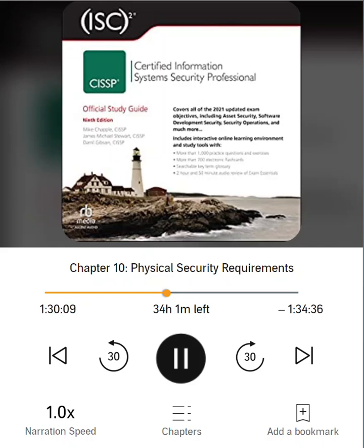Class A. Type: common combustibles. Suppression material: water, soda acid, a dry powder or liquid chemical. Class B. Type: liquids. Suppression material: CO2, halon or alternate gas options, soda acid. Class C. Type: electrical. Suppression material: CO2, halon or alternate gas options.